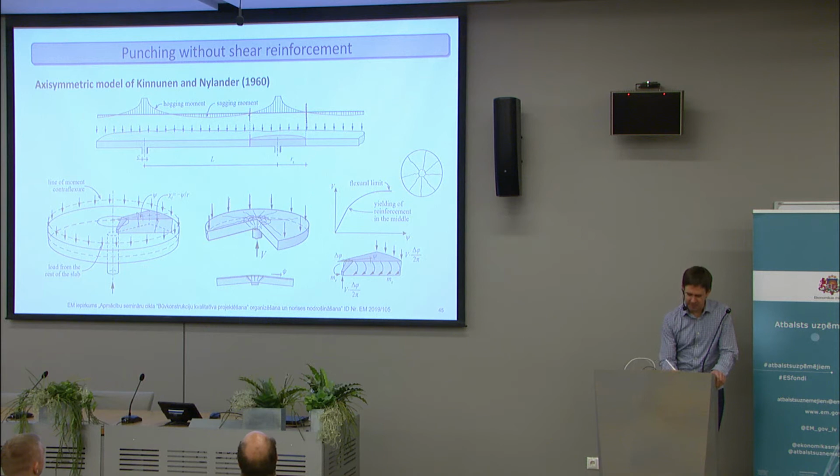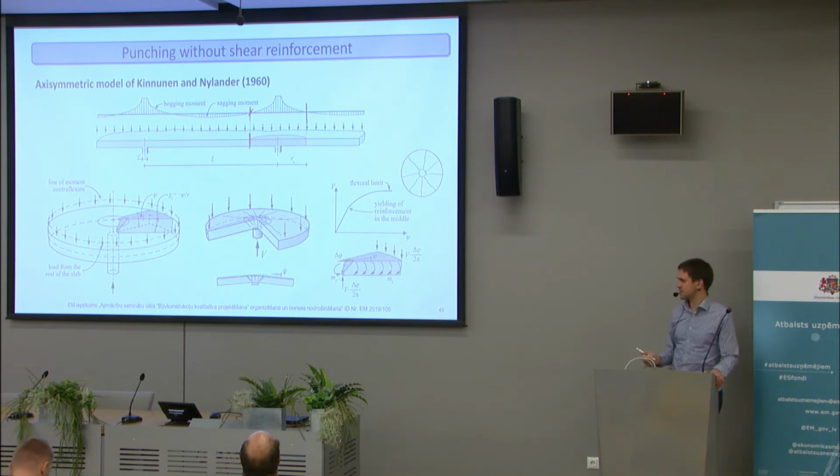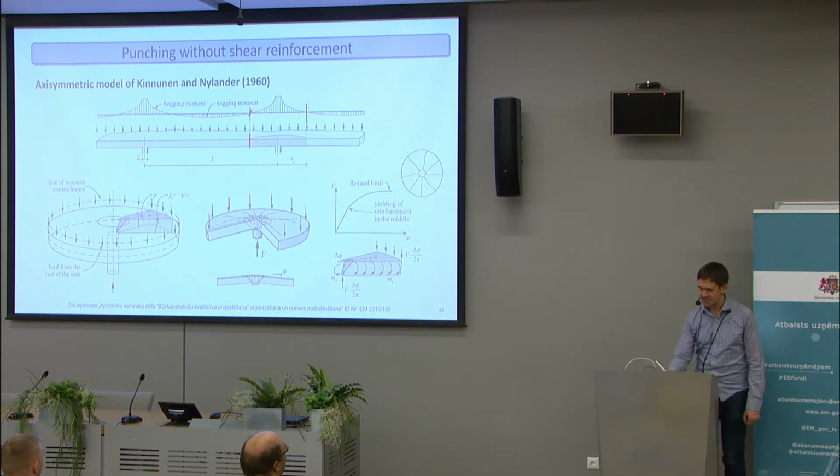So if we look at the distribution of bending moments in a big slab, and we take the part of the slab that has negative moments, then on this perimeter we only have shear forces. The moments are zero. That means if we take this part out, we only have to apply shear forces at the edge, and we get a representative behavior of an actual continuous slab.